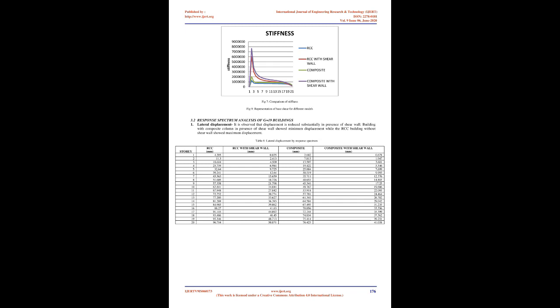The modeling has been done in accordance with IS 456 and IS 1893. The building has a fixed support at the base. The buildings are modeled using software ETABS for Zone 4. Center to center distance between two consecutive columns is 4 m. The columns provided are square as they resist earthquake loading better.